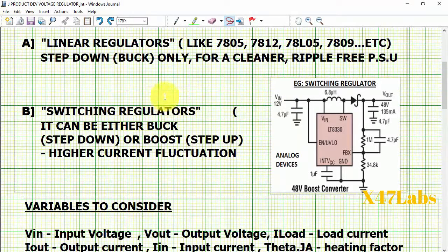These voltage regulators can be divided into two broad classifications. 1. Step-down outputs a voltage lower than the input voltage, and 2. Step-up outputs a voltage greater than the input voltage. Knowing your input and output voltages will help you to easily decide which group your regulator falls under. Voltage regulators that require an output voltage less than the input voltage are the most common type of voltage regulator. For example, you input 5V and it outputs 3.3V, or your input is 12V and it outputs 5V.